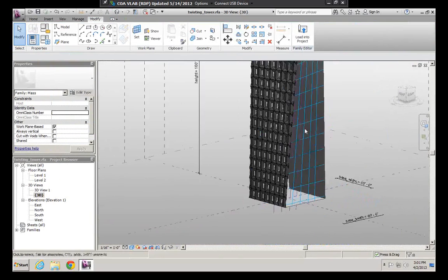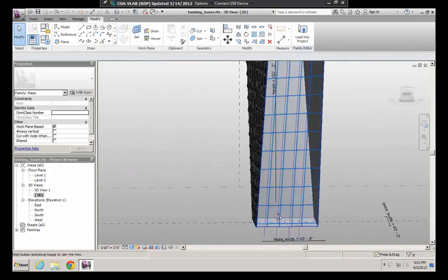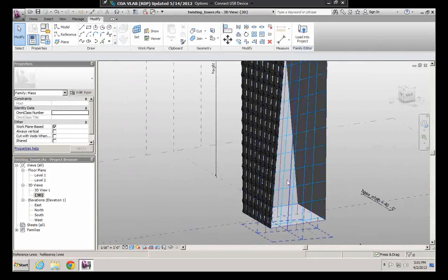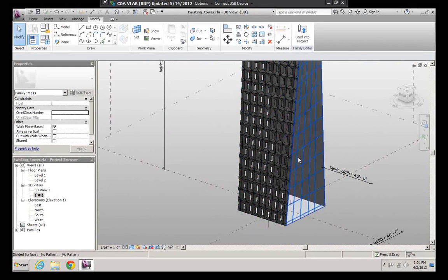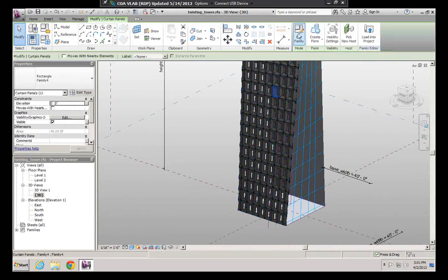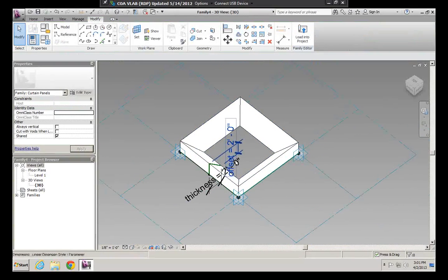So what I want to do now is to see if we could change some of these patterns and apply it to a non-uniform subdivision and see the change. So let's say we go back to our family. So I can simply select one of these tiles and go to edit family. And let's say we want to further develop this. So enter some width and height parameters as reporting parameters, so they could be gathered from the surface, and then have them influence the thickness and offset values.